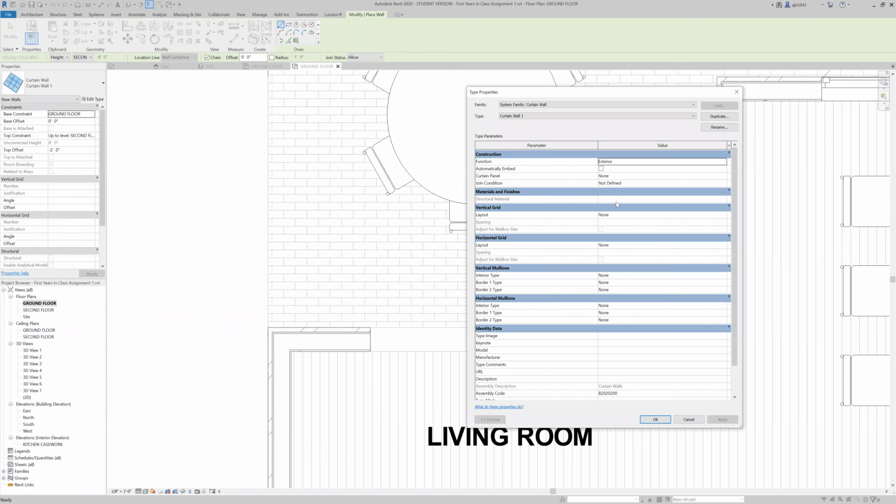We'll go ahead and draw that wall now that we've created the opening. Some of the constraints that you can control within the curtain wall are the vertical and horizontal mullion spaces. You can either set a fixed number that you want to have in there or a fixed distance. So we can choose the fixed number, and Revit will automatically fill those in. And for the horizontal grid, those are the ones going vertically up the wall. We can do a fixed number for that one as well.